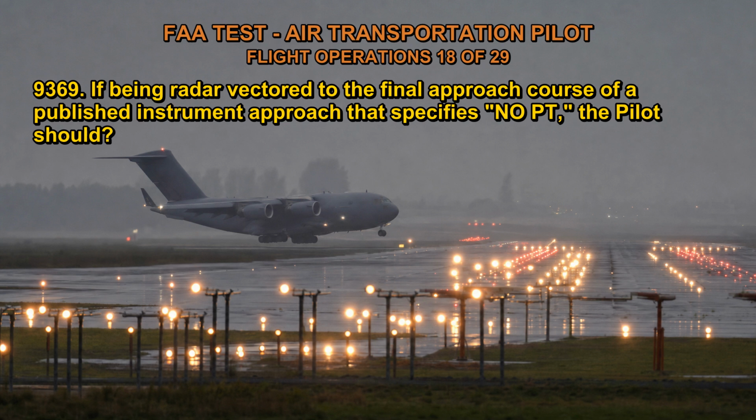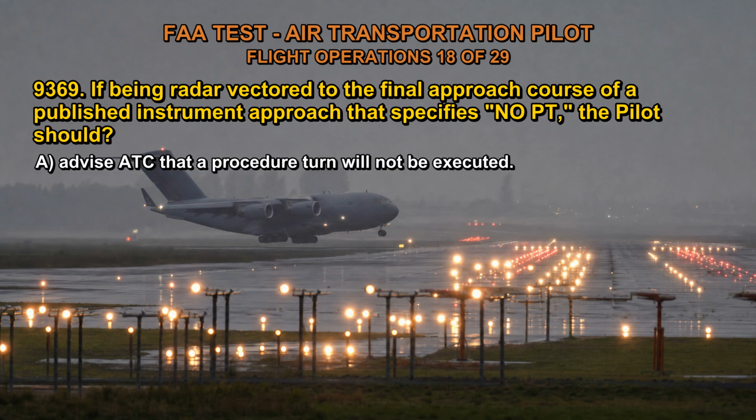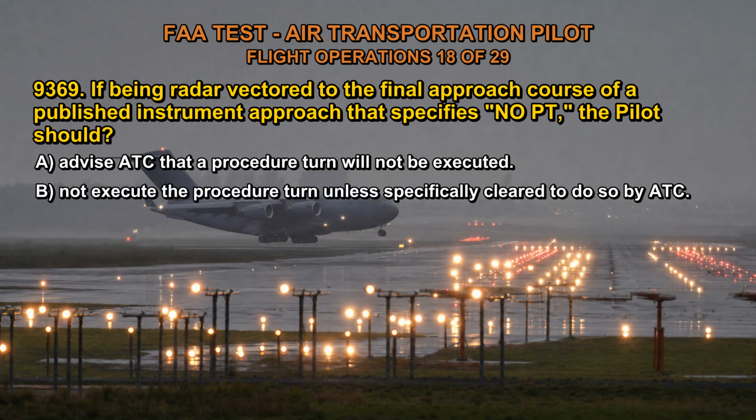Q9369. If being radar vectored to the final approach course of a published instrument approach that specifies an OPT, the pilot should A. Advise ATC that a procedure turn will not be executed. B. Not execute the procedure turn unless specifically cleared to do so by ATC. C. Execute a holding pattern type procedure turn.